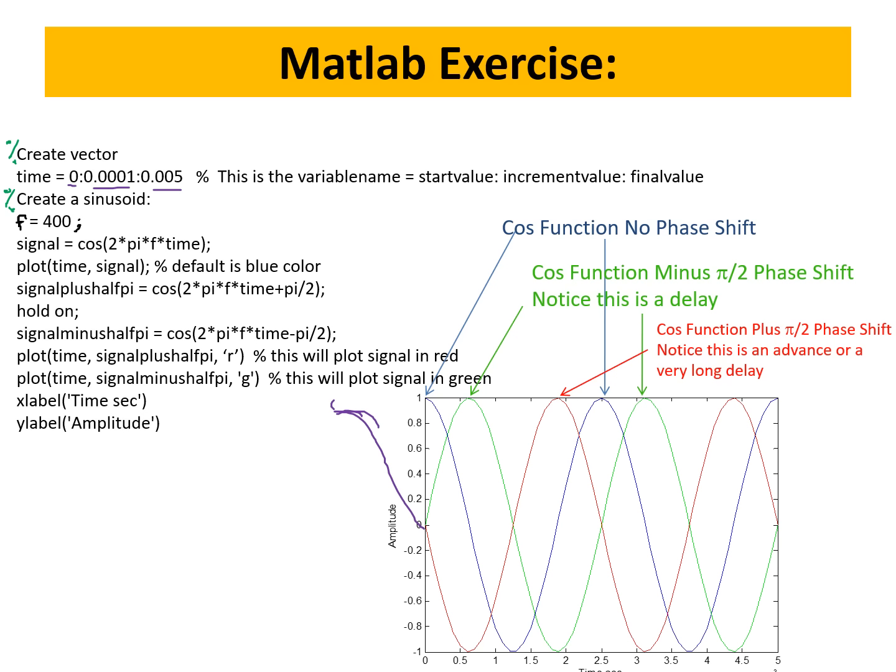If it's negative, the minus, which is the green here, it means it's going to be delayed. So the peak is happening after time equals 0. This is the opposite of what happens with the time shift, but this is how we are looking at the phase. If it's minus pi over 2, that means we have a delay. If it's positive, it's advanced, happening earlier. That's actually similar to what happens with time, plus t or minus t. Minus t is a delay, and plus t is an advance.